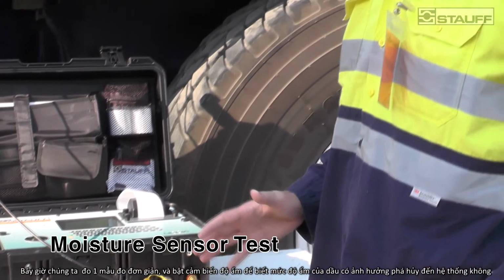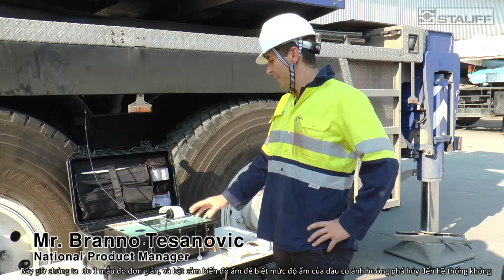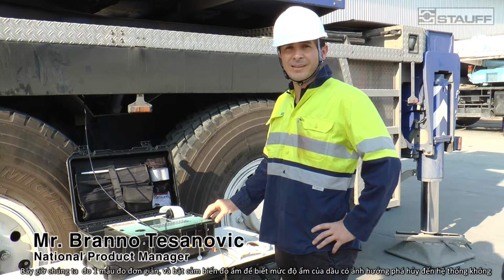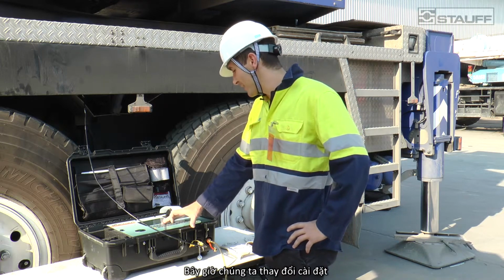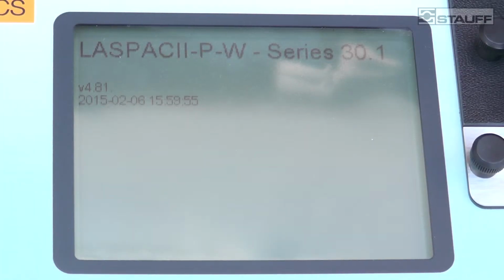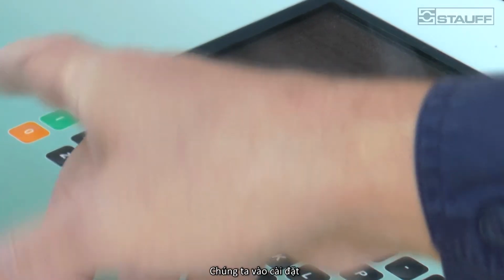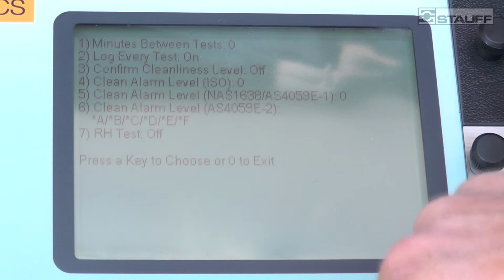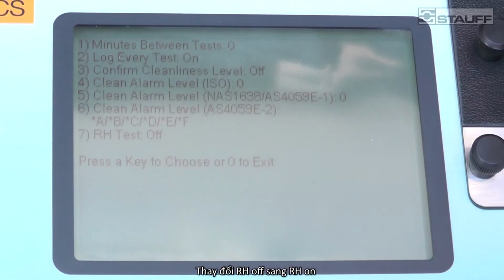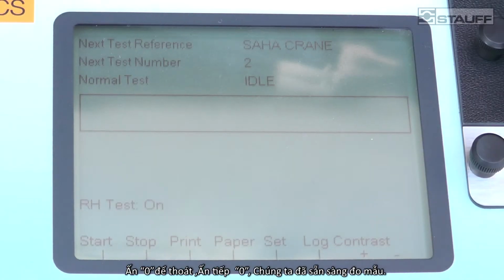So now we're going to do a similar test, but this time we are going to turn our moisture sensor on, as water is also very damaging to our hydraulic system. So we want to see the moisture content of the actual oil. So I just need to change settings. We turn the particle counter on, we go into the settings, and in the test options menu, press 6. Change RH test off to on. So press 7, change to on. Press 0 to exit, 0 to exit again, and we're ready to take the test.